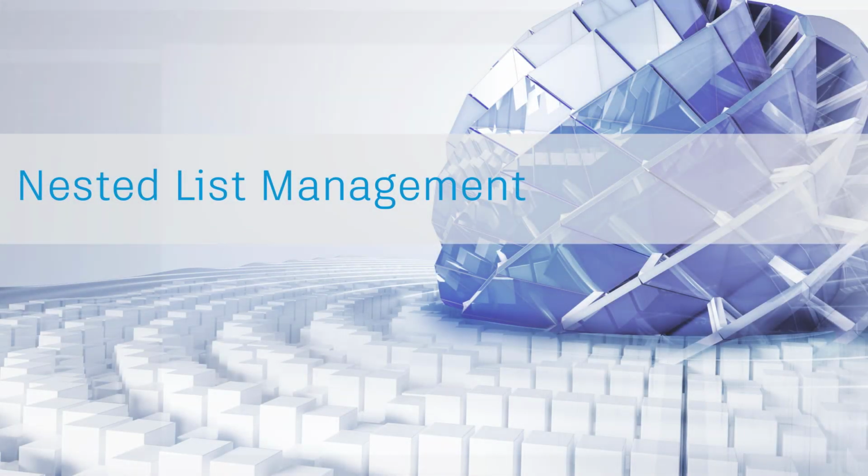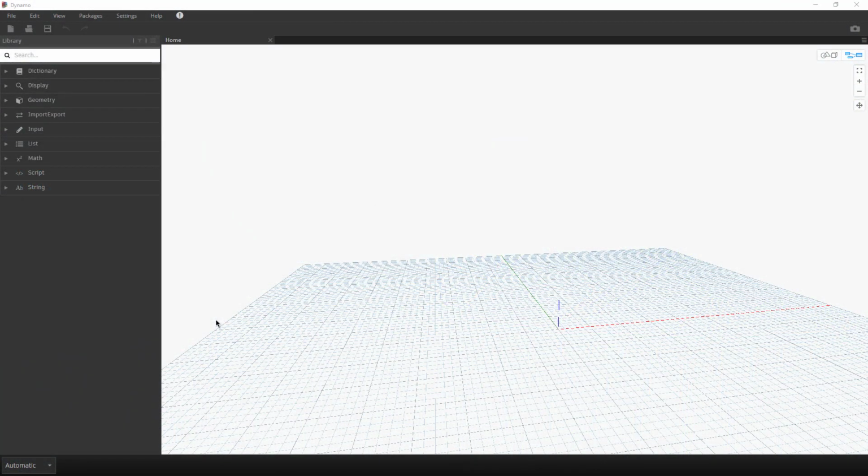In this lesson, we will explore concepts for how to manipulate lists and nested lists in Dynamo for Revit and Dynamo Sandbox. To begin, we're going to construct a sequence of numbers to define an x and y input of a point by coordinates node. To go ahead and do that, we'll use a double click for a code block on the canvas.